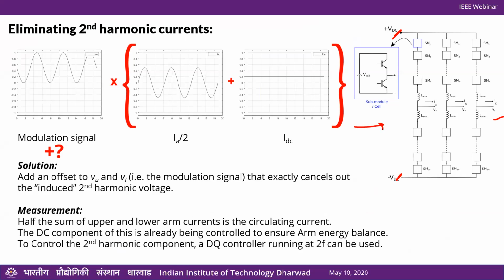That's absolutely possible. The problem is that the application of MMCs is attractive when these voltages here are fairly high. So when this VDC link is fairly high, I'm not sure if it makes sense to have PV outputs, which are right now 1.5 kV.